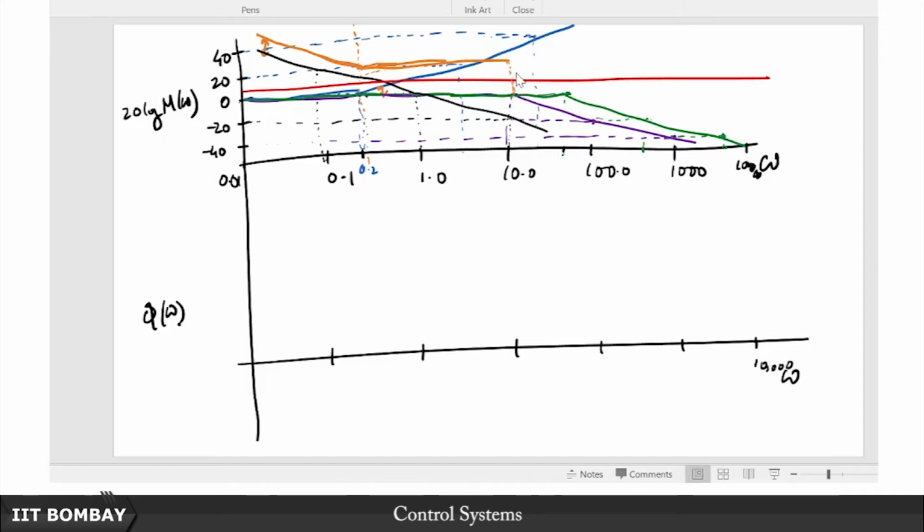So from this constant line that I was following, which was the cumulative plot of this entire system, now something is being taken away. So it's going to fall at minus 20 dB per decade until it encounters this green corner frequency here.